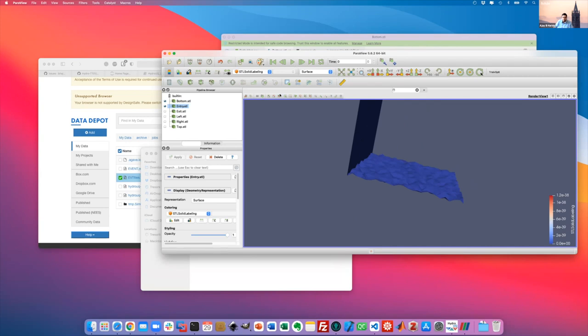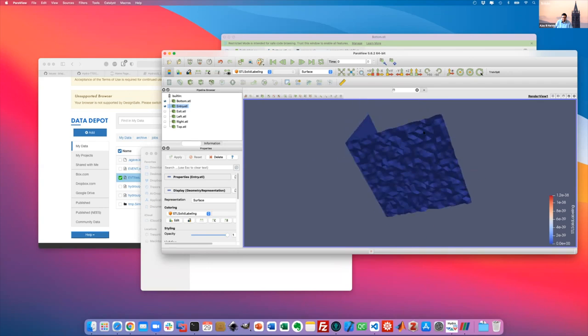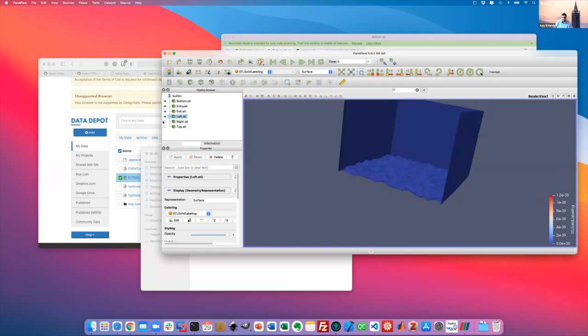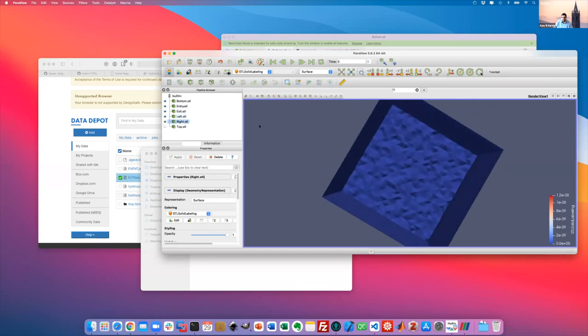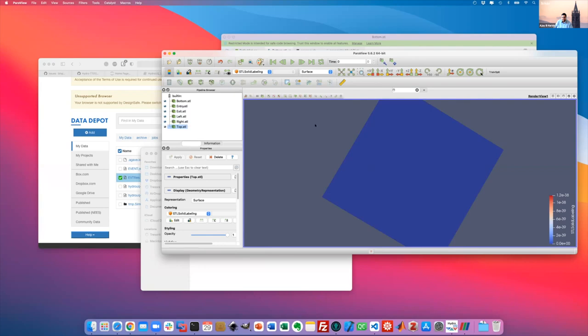That is where, if you, for example, use the HydroUQ to give the bathymetry, it's automatically going to generate it. So this is the bathymetry generated, the STL file of this bathymetry is generated from the HydroUQ, right? So you can see the exit, and then you have a patch for the left, a patch for the right, and then you have something for the top, right? So these are the 6 patches. It's going to combine these and mesh this thing. That forms our total geometry that is going to be meshed.